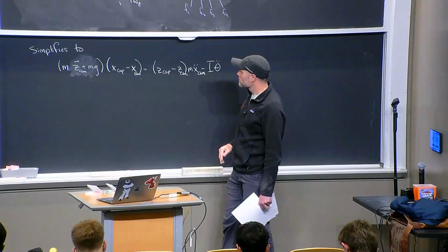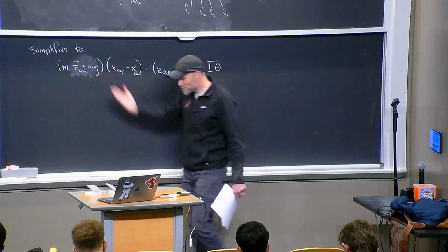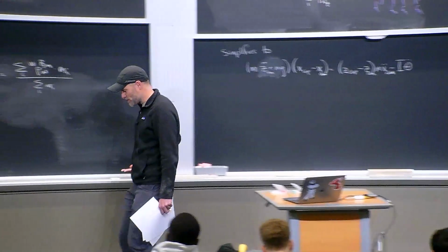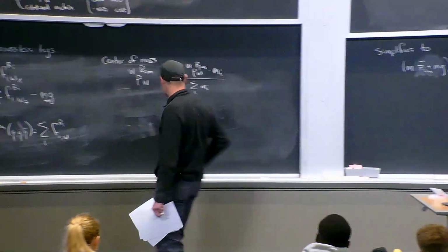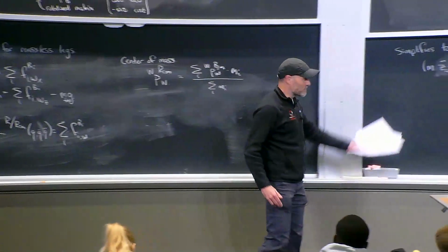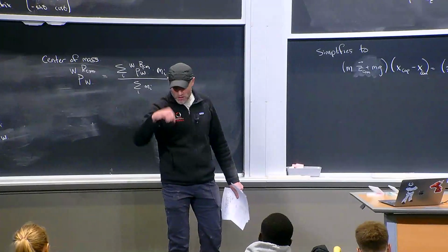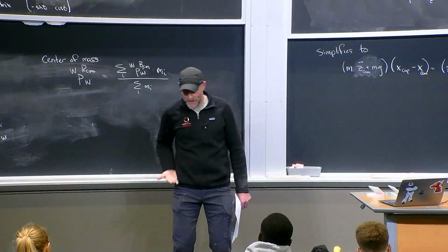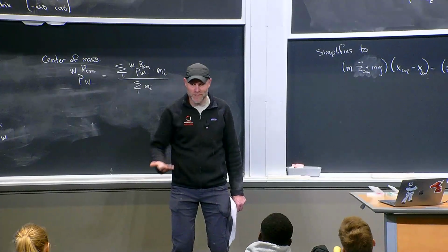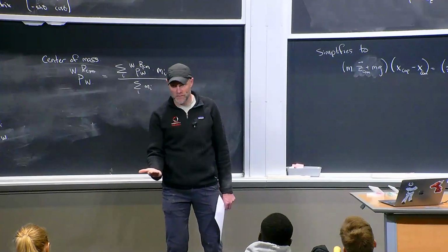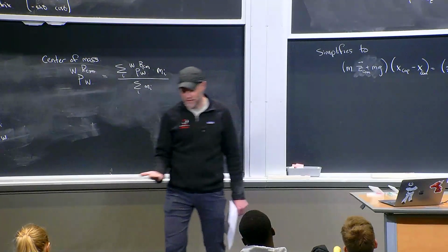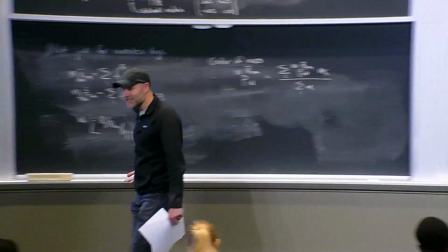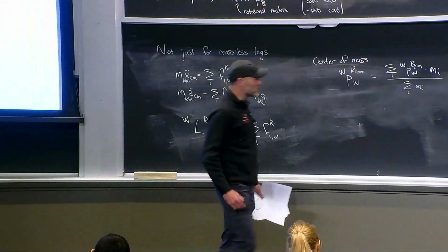It turns out if your center of mass stays at a constant height, and you keep your angular momentum small, then those dynamics linearize, and you can do LQR, you can do model predictive control, you can do a lot of planning of your center of mass trajectory using linear techniques. So kinematic singularity is one, and doing linear planning is the second reason why those robots walk like that.